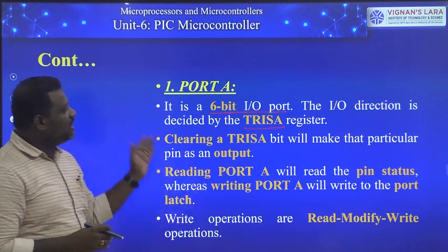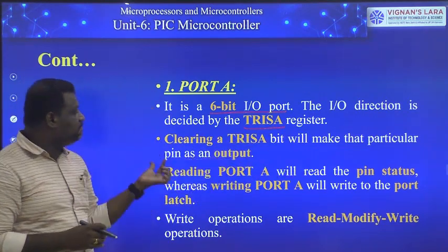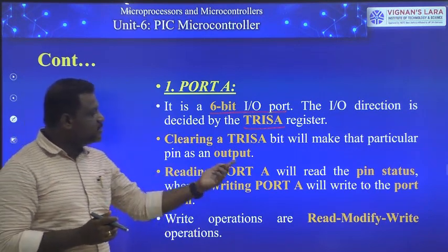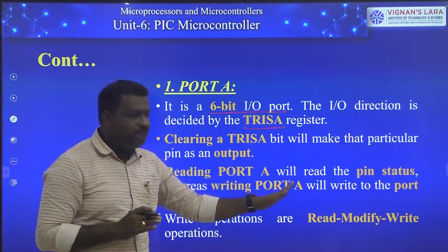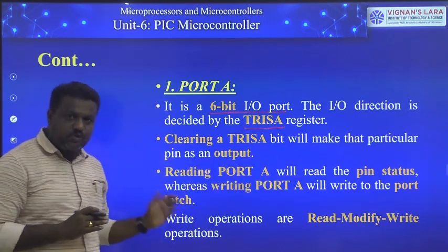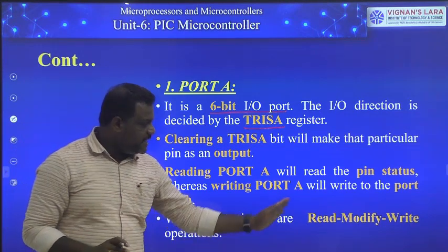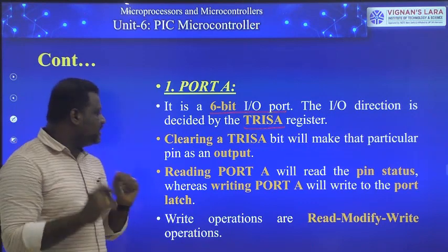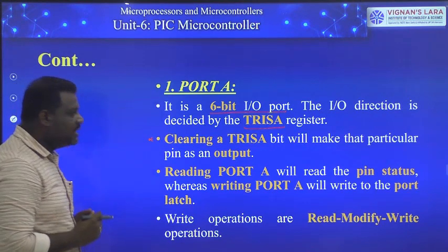Clearing a TRISA bit will make that particular pin an output pin. Reading port A will read the pin status, whereas writing port A will write to the port latch. Write operations are always read-modify-write operations. Let me discuss this point a little bit.